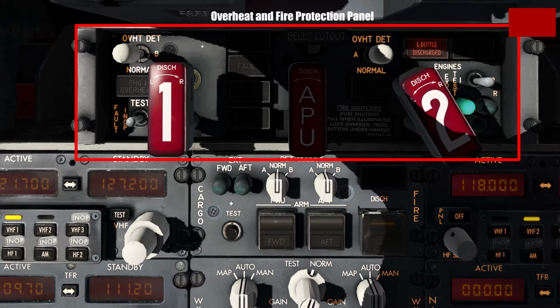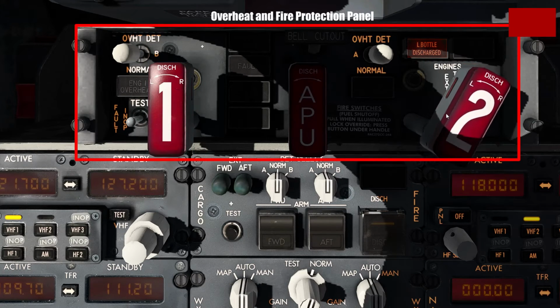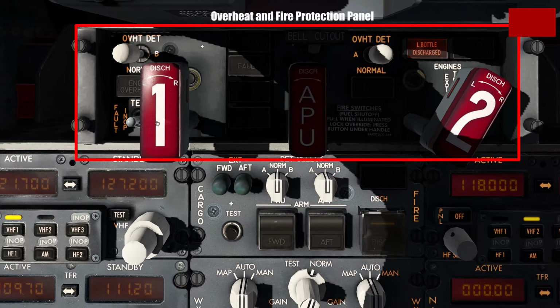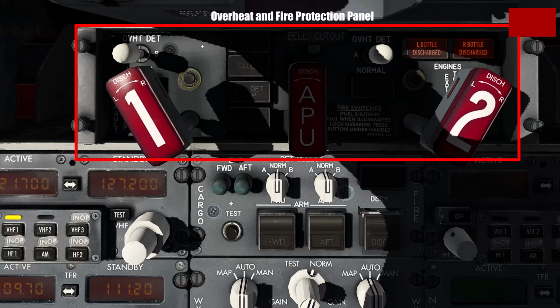When twisted to the left, as we have done, it lights up this light over here to signify which extinguisher bottle has been used, and this green light is an additional visual cue for the pilots to see that the right engine's fire has been extinguished. Note that firstly, these buttons can only be pulled backward when the automatic fire detection loops in the aircraft actually detect a fire. This is to prevent the pilots from accidentally pulling these switches and disconnecting the entire engine from the aircraft, which can be very costly to the airline, as you can imagine.